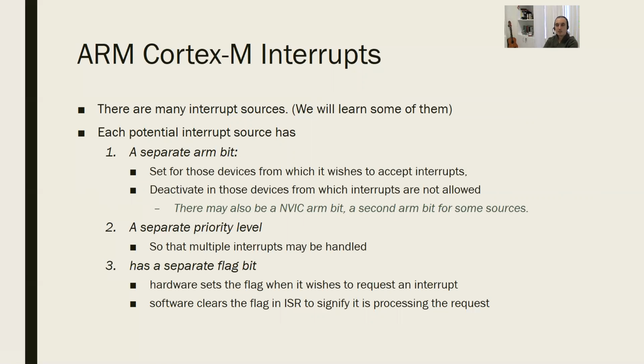Exactly. To the stack. And actually, be careful, guys. You can save all register values to stack, right? You do push stack and pop stack, but it is not you doing it. It happens automatically. The system is designed to do it. You just create the necessary modifications in control registers so that the interrupt can be accepted. When the interrupt is accepted, they're automatically done. There is a mechanism already hard-coded in the device. That's what interrupt is called. And we are going to see every detail of that mechanism. First, we are trying to understand the theoretical background of interrupts. Okay?